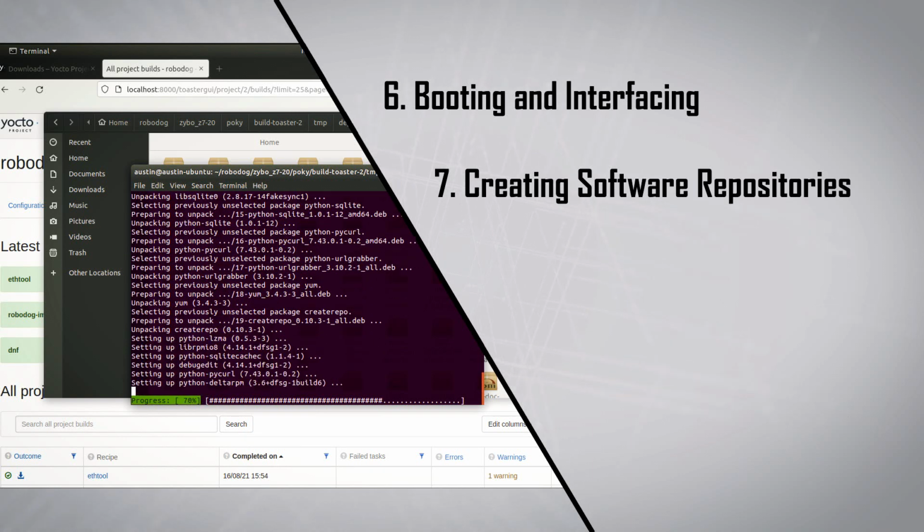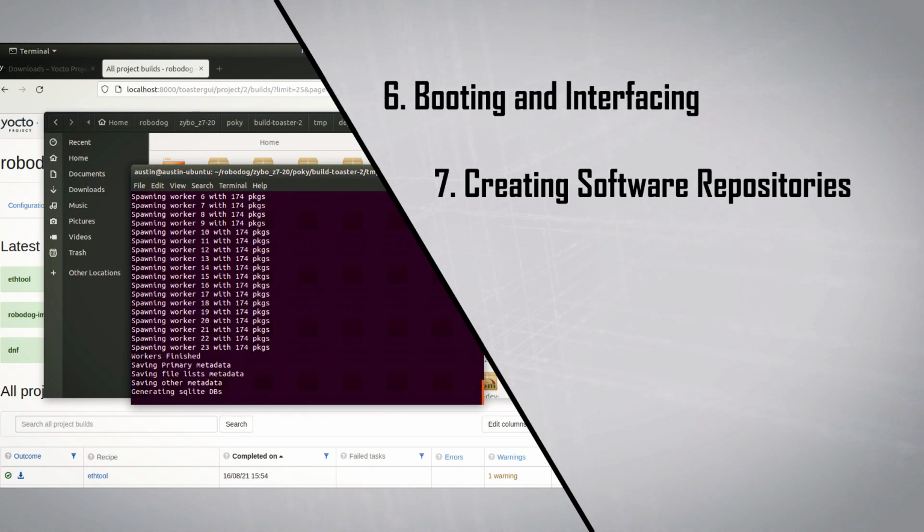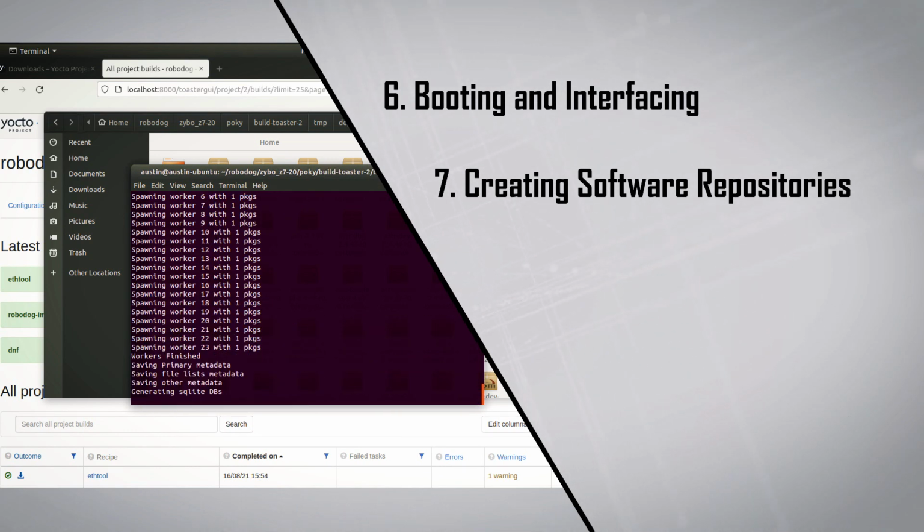I'll also show you how to update and maintain your own software package repositories so that you can install software packages on your embedded platform over Ethernet during runtime. This will help speed up your development so you don't have to reflash the SD card every single time you want a new software package.